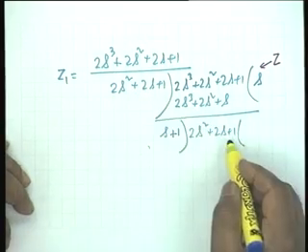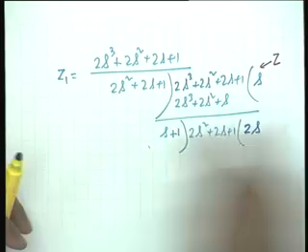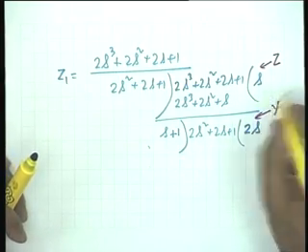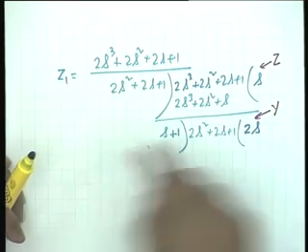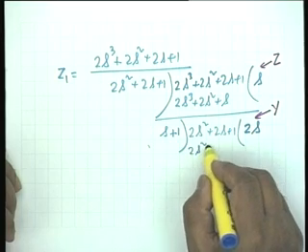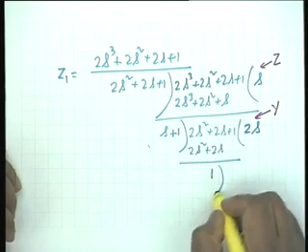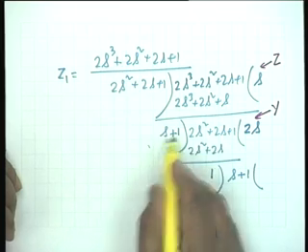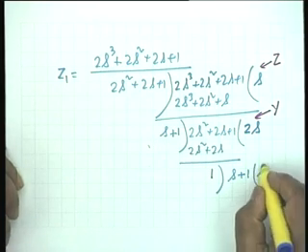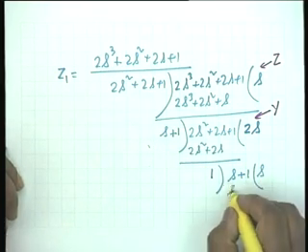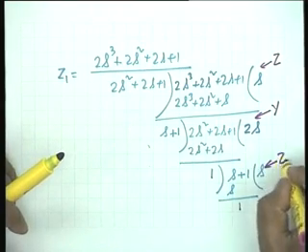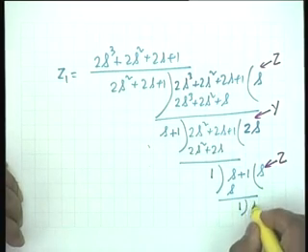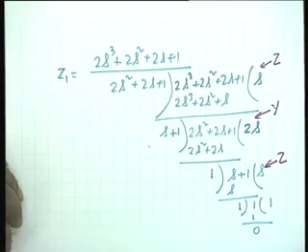Okay. This you bring here, then the quotient is 2s, and immediately you identify that this is an admittance because you have taken the reciprocal of an impedance. So you get 2s squared plus 2s and you are left with 1, then you bring this divisor here and your quotient is s, remainder is 1, and you immediately identify this as an impedance, then you divide 1 by 1, 1, 1, 0, and the continued fraction expansion is over.